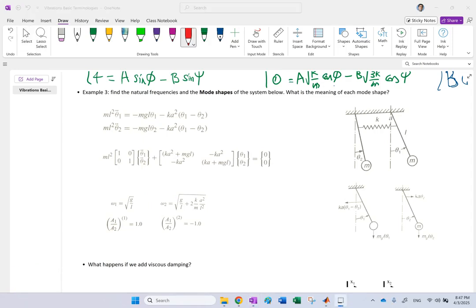next example, which is two pendula, one with theta 1, one with theta 2, and they are linked by this spring K. If this spring was not there, each one would do its separate motion. You wouldn't really call it a 2DOF system because they are not linked together. It's not a system, it's two separate systems. But because this spring is linking them together, now it's one system with 2DOF, and there will be vibrations now because there is some force that is restoring these positions back in addition to the mg.